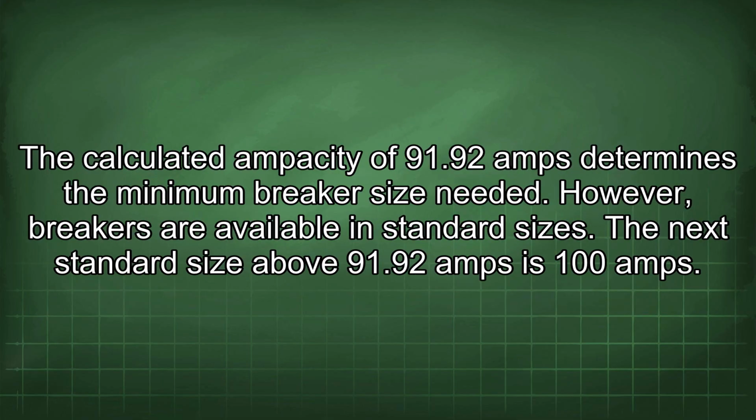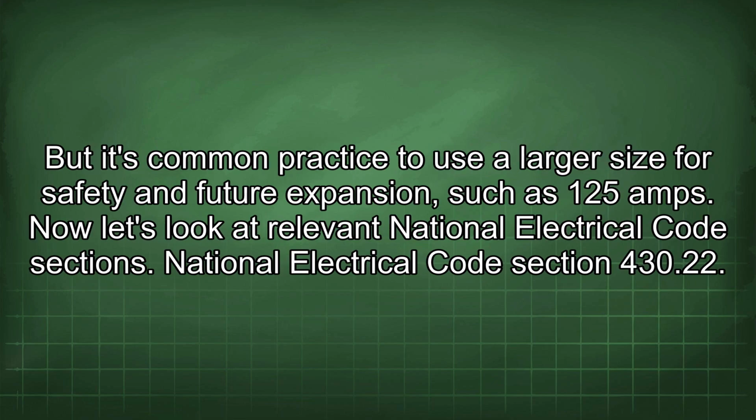The calculated ampacity of 91.92 amps determines the minimum breaker size needed. However, breakers are available in standard sizes. The next standard size above 91.92 amps is 100 amps. But it's common practice to use a larger size for safety and future expansion, such as 125 amps.